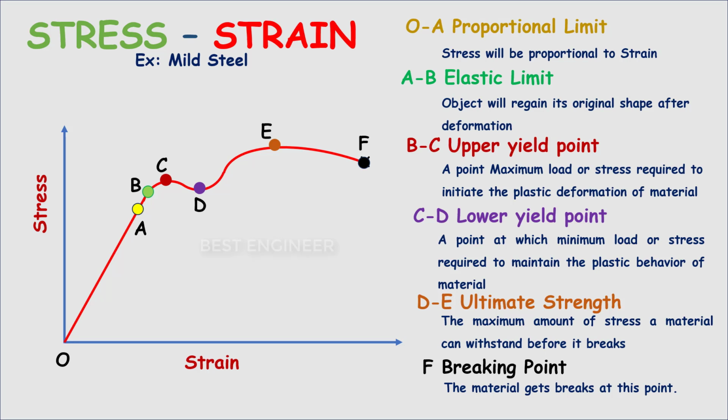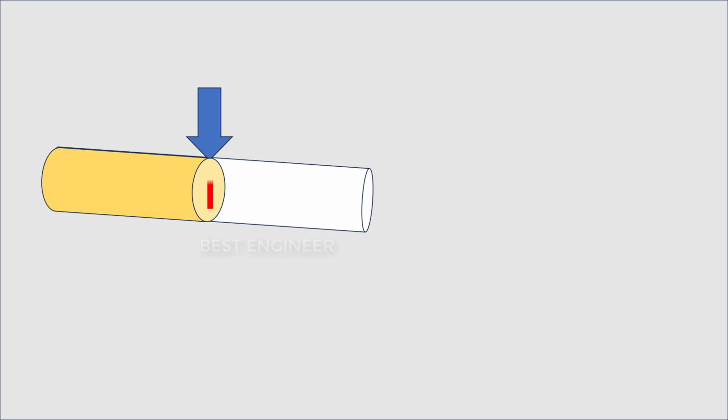So far, we discussed the normal stress. Imagine a rod where the force is acting in the lateral direction of the axis. Now due to the load the rod will slice like this. The induced stress is called shear stress and the strain is called shear strain. In this, the shear force will be developed parallel to the area of the rod. This shear force is common in bolt and nut arrangements.